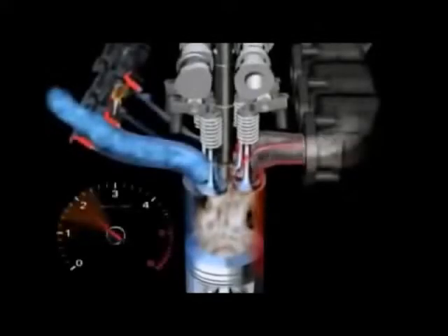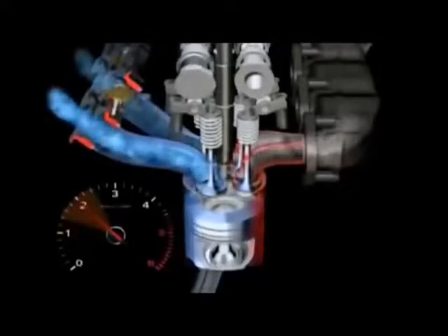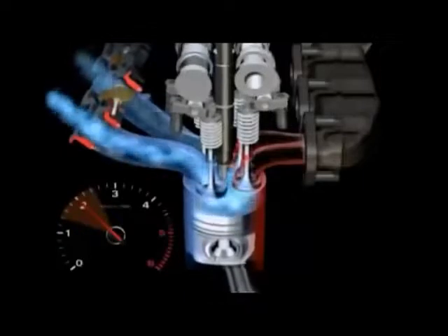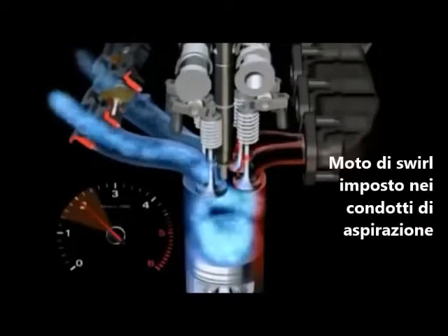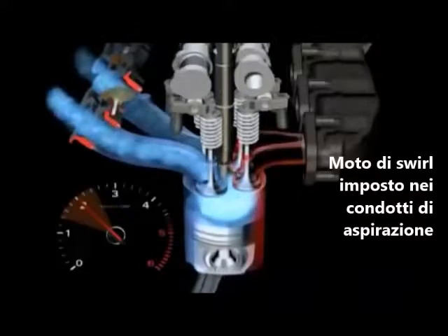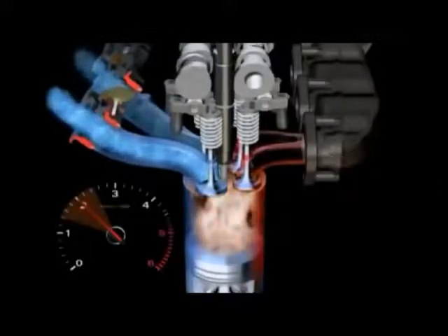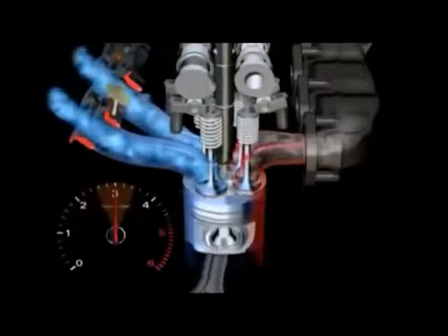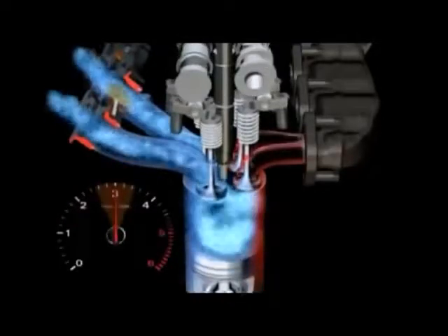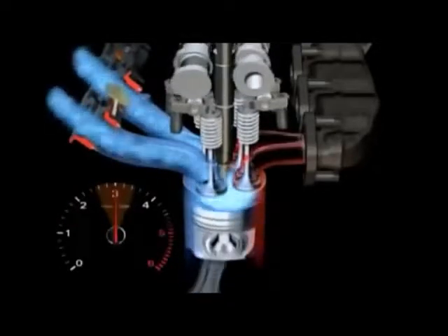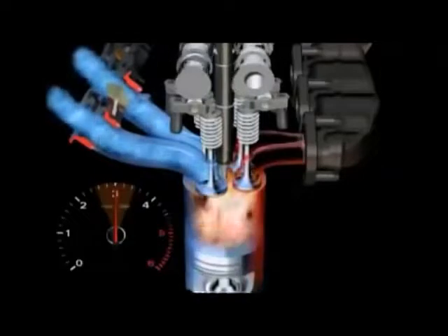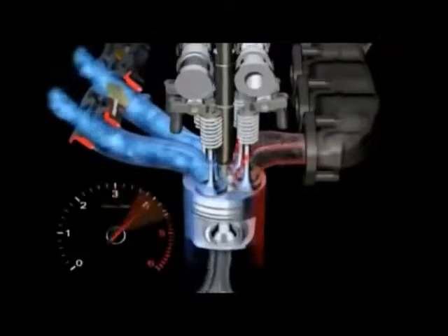The TDI turbochargers are part of a new generation. In the intake manifold of the engine, there are swirl flaps which are used to regulate the inflow of air in order to achieve optimal combustion. This use of technology allows high maximum torque at 5,400 rpm and clearly improves the thermodynamics in the combustion chambers. It allows the engine to run with a very high rate of back-fed and heavily cooled exhaust gas.